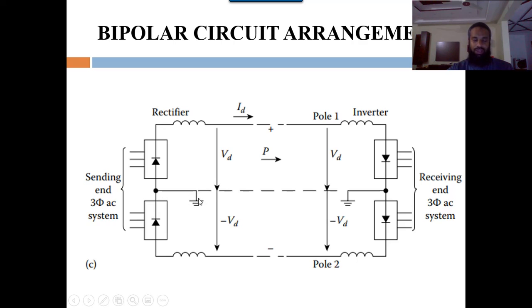But if you see, there is ground on the input side, and similarly ground on the output side. So in between the input and the output side there is a virtual ground. We should keep this in mind: if the system is balanced, that means the current in the upper side of the transmission line and the lower side of the transmission line is the same, then it will cancel its effect, and there is no current travelling in the ground line.